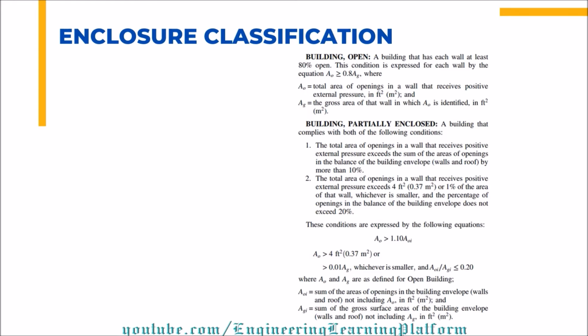If your particular wall has an opening so large that, when we compare its area with all other opening areas of your building, it is 10% more than those combined, then this is the first condition for a building to be partially enclosed. Means any particular wall should have an area of opening more than 10% of the total area of opening in a building. That's your first criterion.